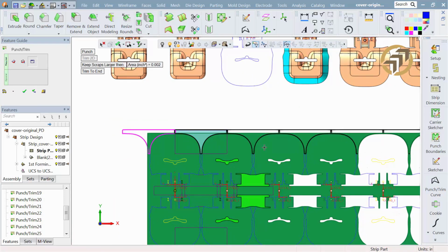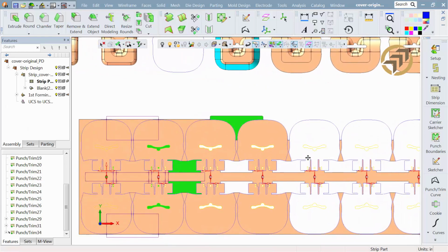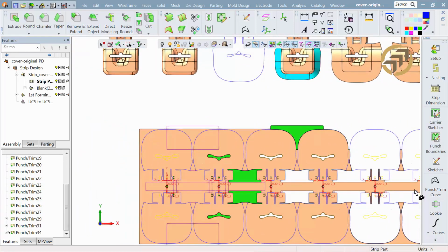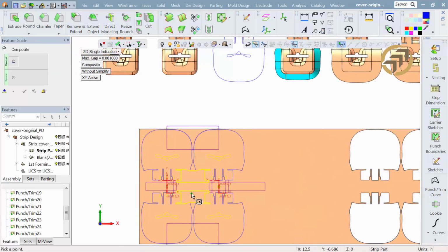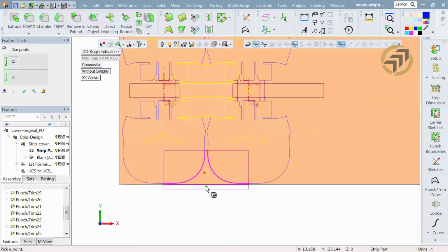And you can see here in the punch display that the overlap is there. That's exactly what I want. We'll go ahead and position it. And that's done. Now you see how it's carried on down the strip as well. Again, in picking the punch area, notice I pick inside a zone, it captures it, then I pick in an adjacent zone and it stretches it out further. So a very intuitive tool to help me build this up.